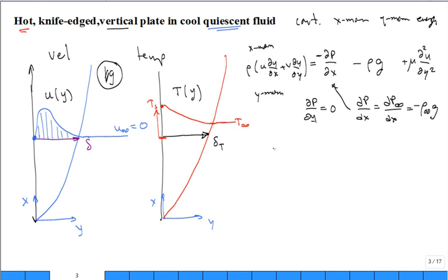And when we do that, we still get the advection term equal to, and what do we pick up? We pick up rho infinity minus rho times g plus the viscosity term. So these two terms combine to this term. Now you can see it starting to take shape. Oh, if the rho is lower inside the boundary layer where it's warmer, then I'm going to get a forcing term to drive the convection. Right? We introduce a parameter called beta. I'm going to talk more about it, but it's on the next page.